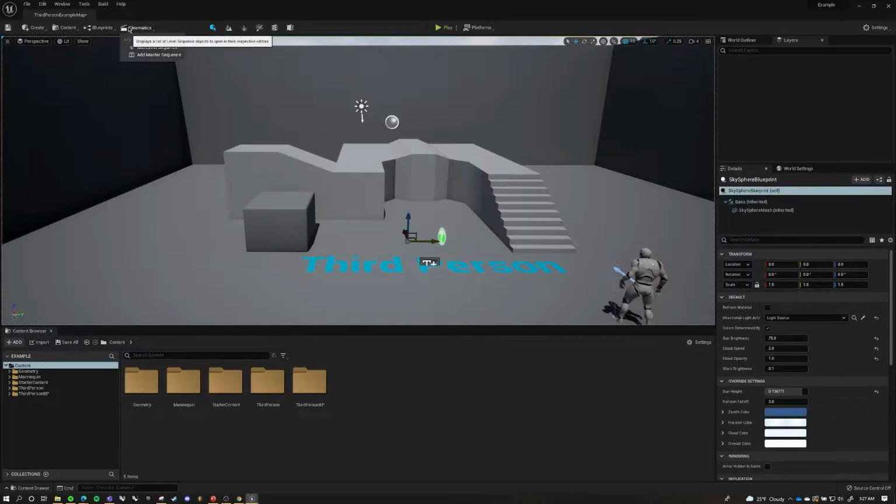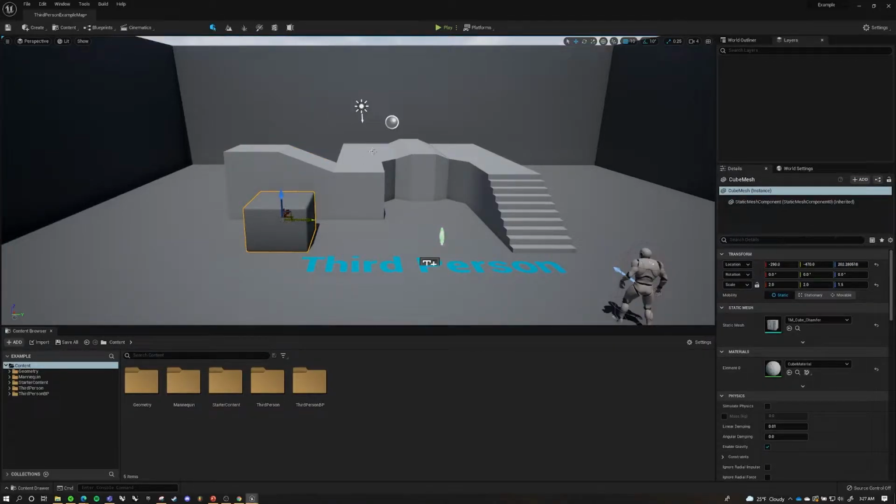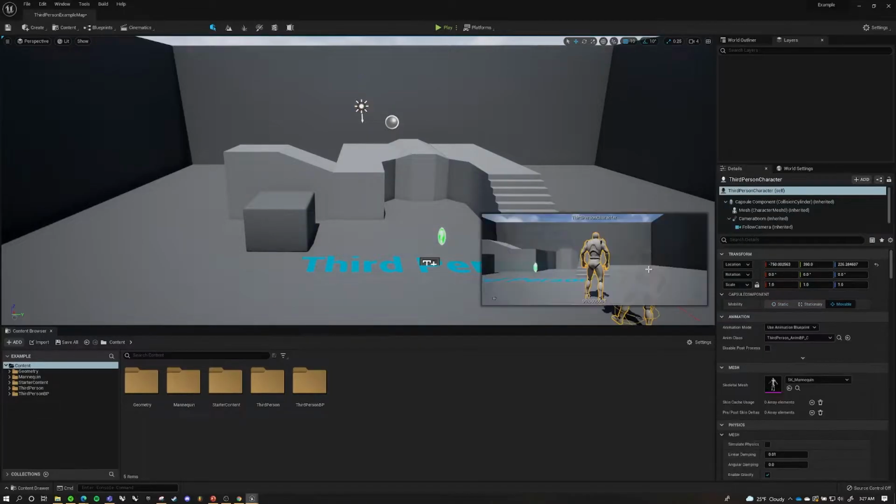Last is the Cinematics tab. This is where you can create a camera sequence, much like the Set Path Animation command in Rhino. Moving on, let's take a look at the main editing modes. They are the buttons just to the right. The first of the buttons is the default mode. It allows you to select objects and adjust their positions, scales, or copy them and such.